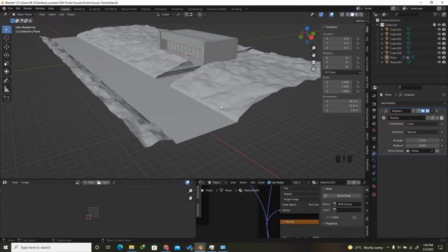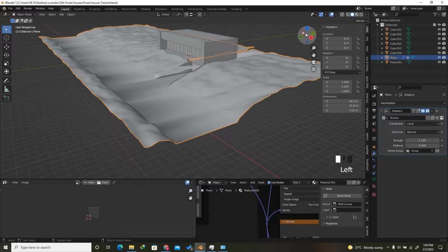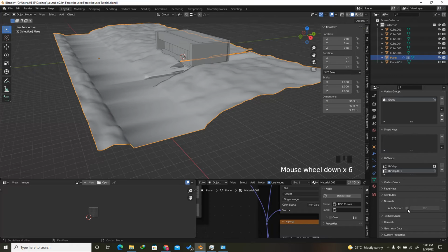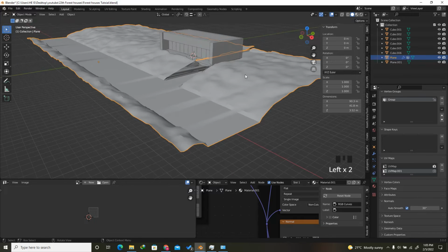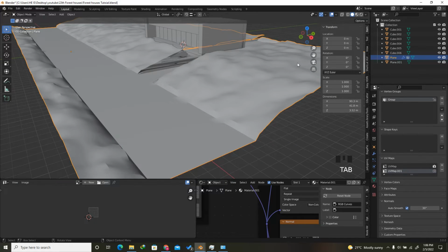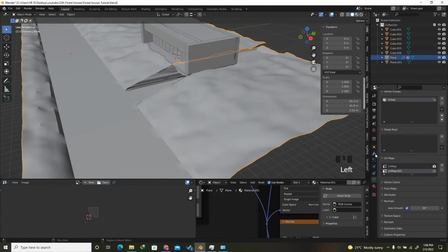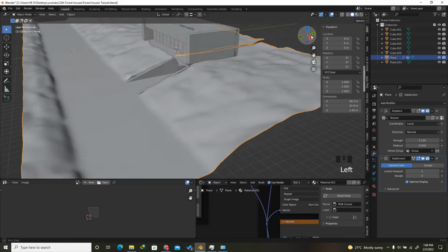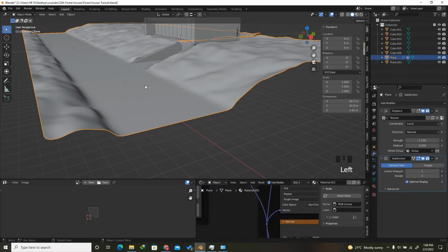So I can control the scale, as I have said. Just right click and then Shade Smooth. Select this one, right click and Shade Smooth so that it will be smooth. In the normals, you can adjust the auto smooth so that it will be smoother. I can give it subdivisions along the x-axis so that it will be more smooth. After this, I can also give it a subdivision surface so that it will be smoother, and we won't see that seam between the road and the turn.